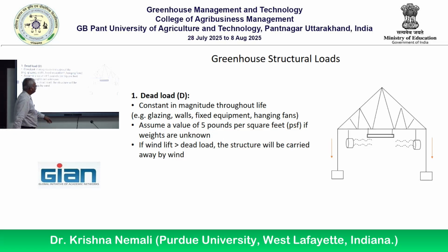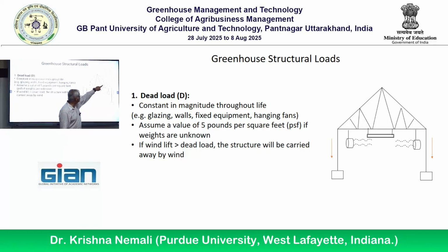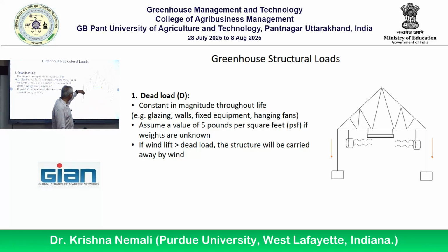Again, keep in mind, this is your structure, kind of like a cartoon here. What's happening? The structural elements are supporting the roof. The weight of the roof is falling on these structural elements. The weight of the structural, like struts and cords, is falling on the side posts, and then the weight of the side post is transmitted to your foundation.